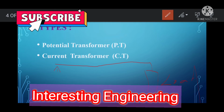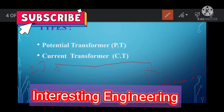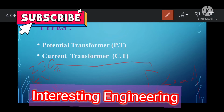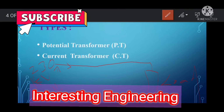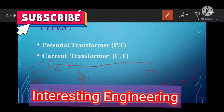Here we have a higher voltage range of about 230 kilovolts. If we want to measure these higher values from this power line, then we have to introduce a potential transformer. This potential transformer consists of a number of turns of primary winding connected across the line.